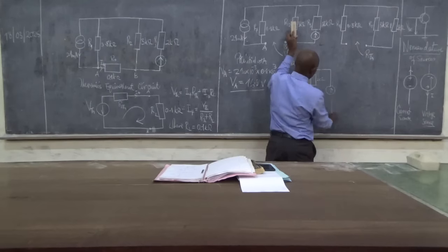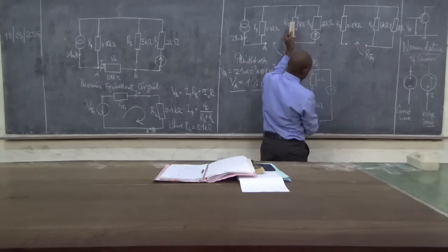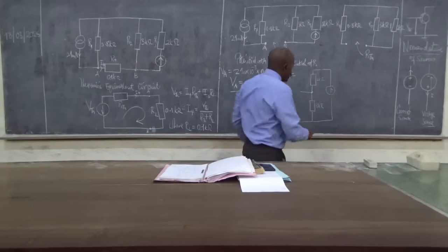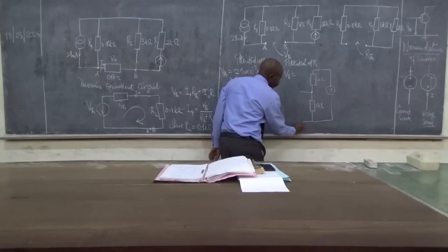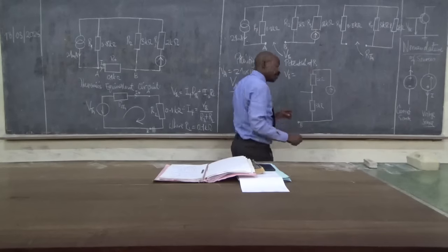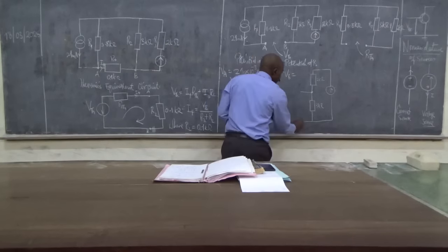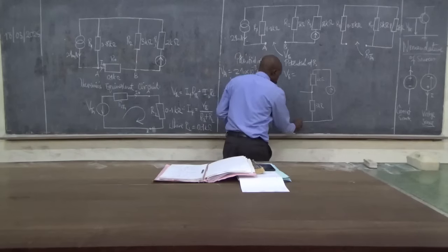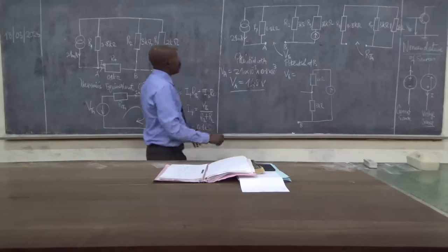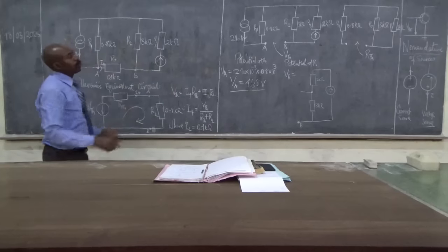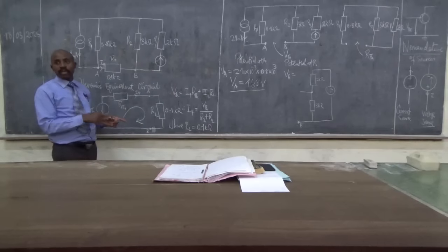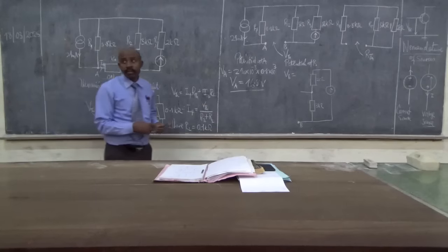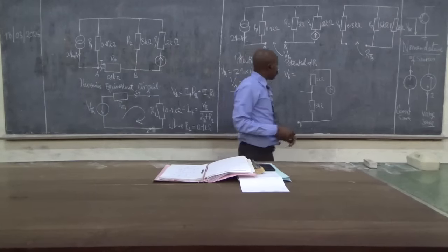And then I have my point B here. This is the reason we recover the potential divider. So in the other case of the superposition principle, you would have to use the current divider. Here we use the potential divider.